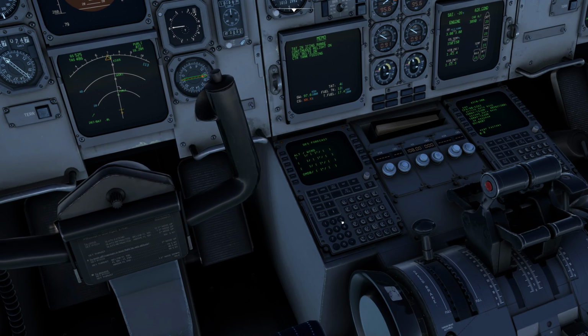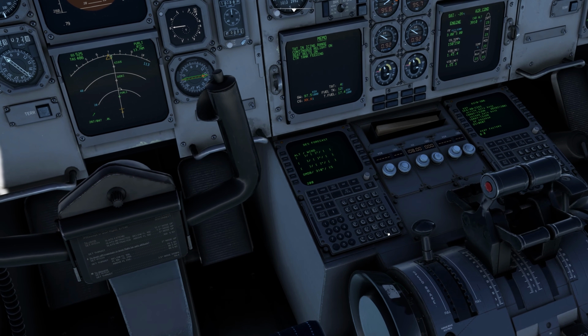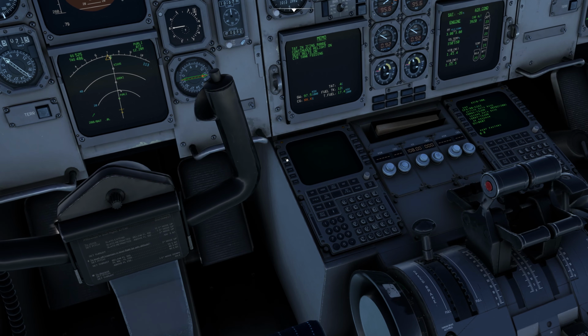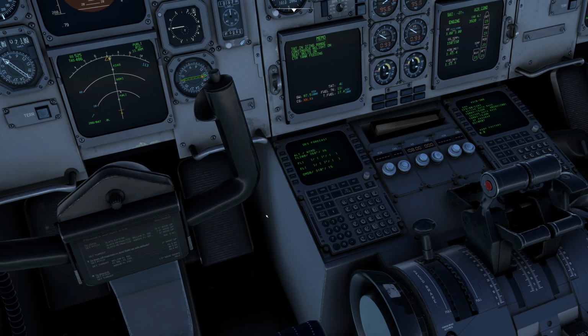It's 310 degrees, 310/015, or you can also enter 15, and it will pick up the wind information. And at different altitudes, you have to enter the same format, 200 for 20,000, / 268 degrees / 026. This is for flight level 200 or 20,000 feet.